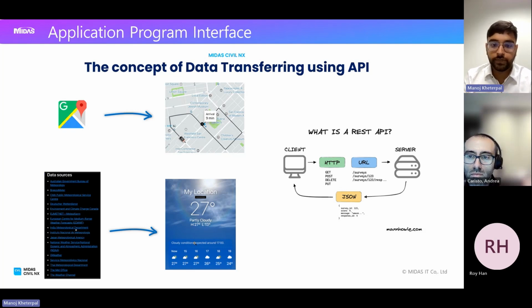you will be using the get command, and then you will be using the put command to update an existing resource, let's say a boundary condition or anything. And let's say if you want to delete anything in the model, you will be using the delete command. So that's what an API is doing. So you must be getting that clear picture that all these four features will be enough to update everything inside the model and get every information from the model.